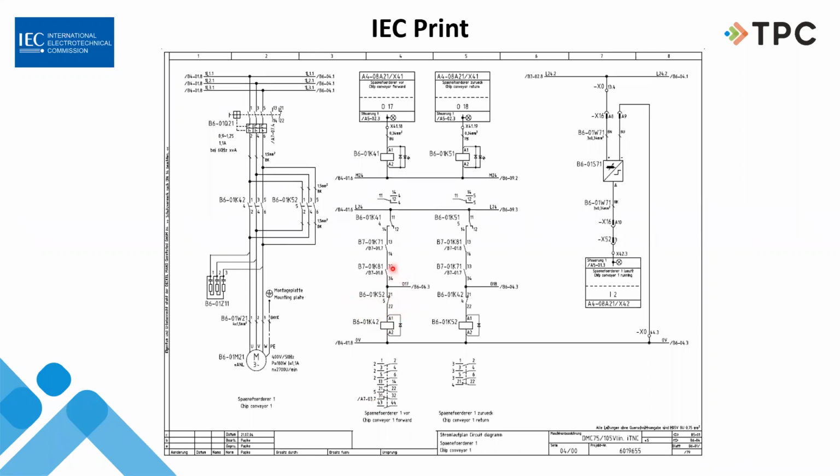All of these, this is the third set. That's the first set on the relay. Again, first set, second set, third set, it gives us all this information. In here, it's even telling us that we've got power from right here going to a different drawing and a different group. It's a B group, page 6. Okay, so we're going to B6 in this case.